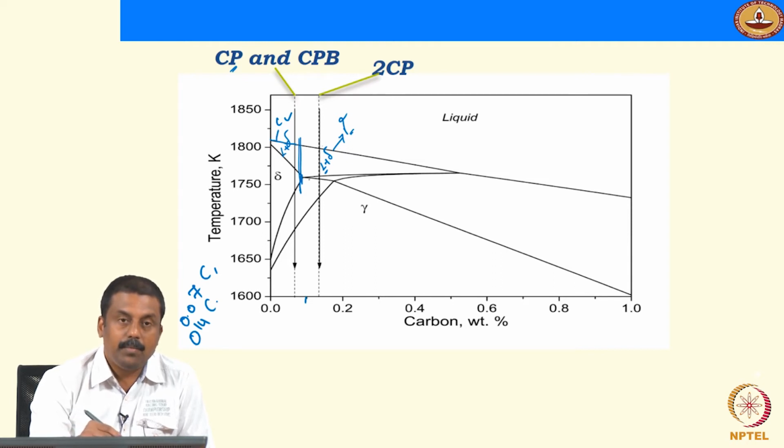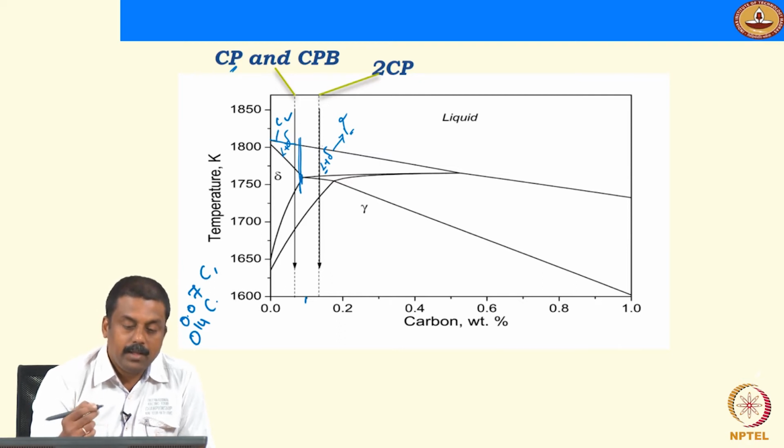So the solidification mode has a significant role in the carbon partitioning in the unsolidified liquid during solidification. When you have solidification directly to complete delta ferrite, the microstructure becomes 100% delta ferrite and subsequently transforms to austenite, and you may expect a larger segregation of carbon in the liquid during solidification.